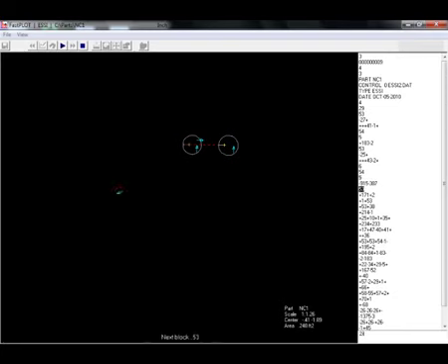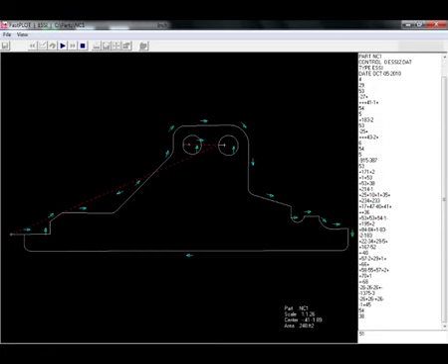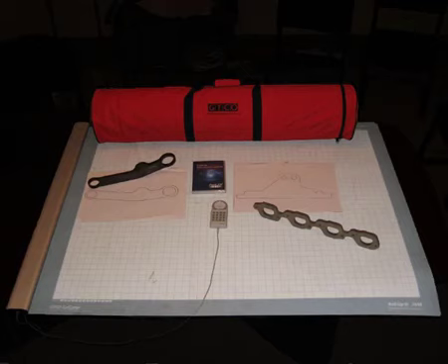The NC is on the right. You can see the directions and that the torch is on the correct side of the cut at all times, or the part size will be wrong. Inside for holes, outside for profiles. Easy? We hope so. Fast Copy, an essential tool for many. All the simplicity of optical with the productivity of NC.